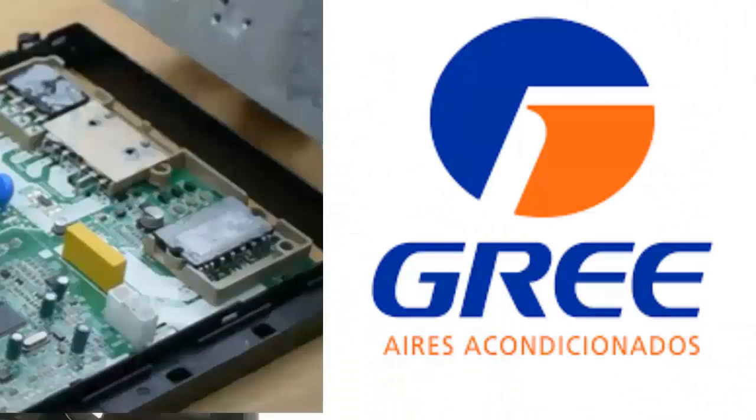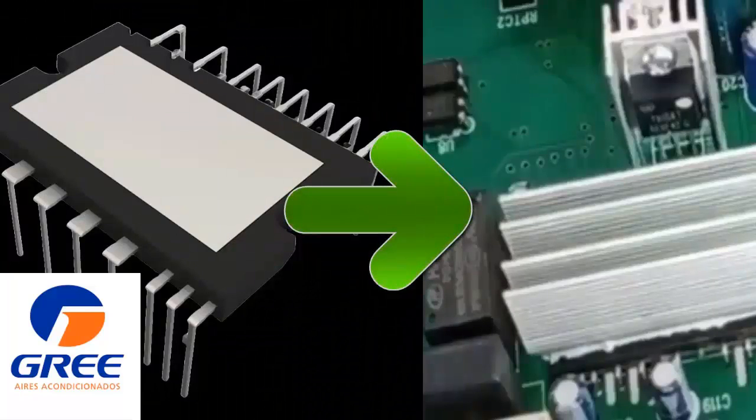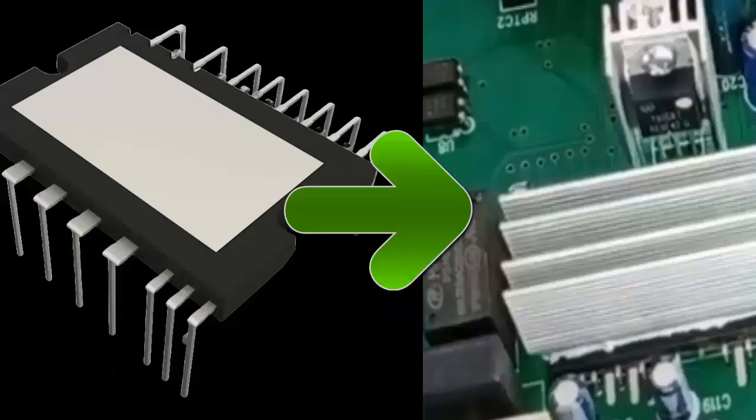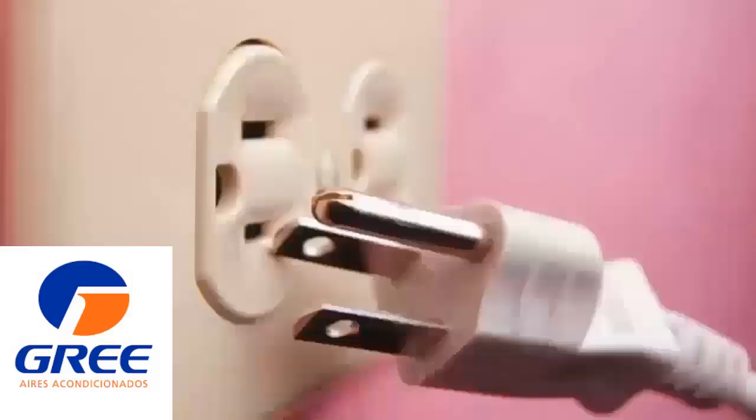Before checking the electrical status of the IPM, it is recommended to verify if the heat exchanger or fins are in the correct position and to check the condition of the thermal paste. This is important because loose fins will impede heat dissipation, increasing the temperature of the electronic module and generating the error code. To verify the IPM electronic module, follow these steps.